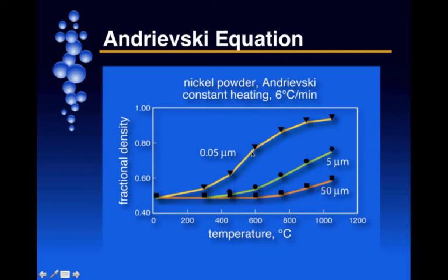But in this case, you can see that you're going almost 500 degrees extra to be able to achieve that type of density of over 0.7. So basically, you need fine particle sizes to accelerate densification. From this, you can see the benefits of going into the nanoscale. You can get rapid sintering, assuming that you can retain purity of the powders.